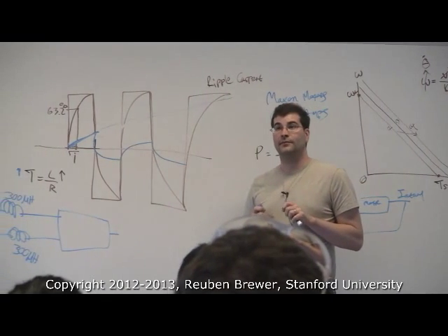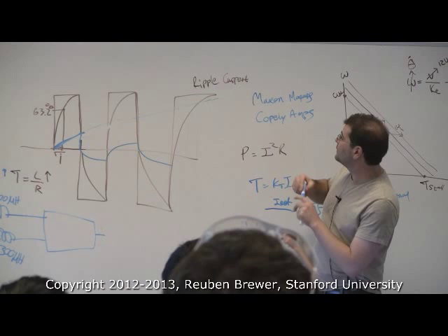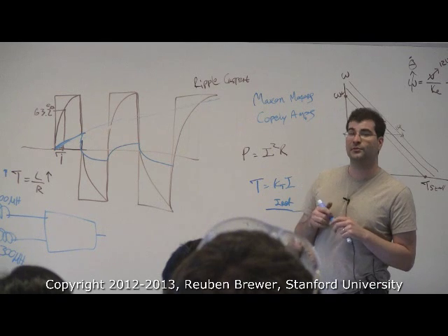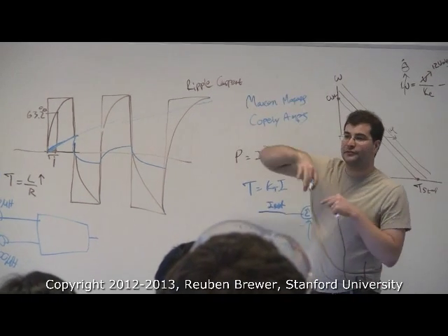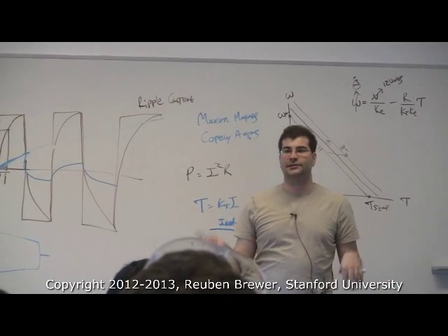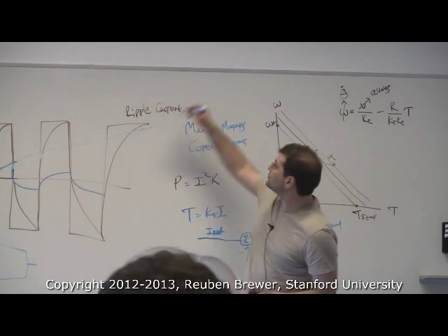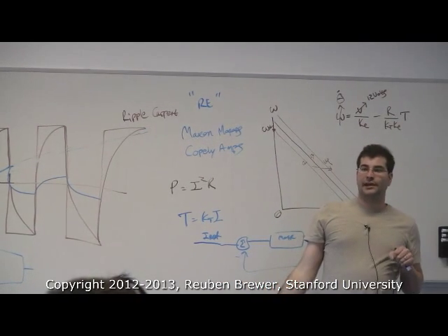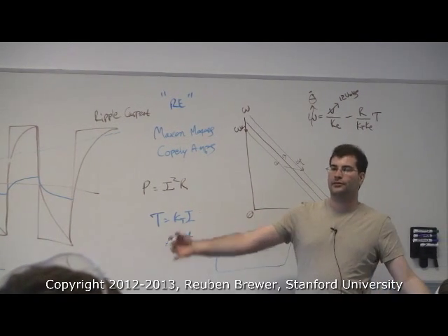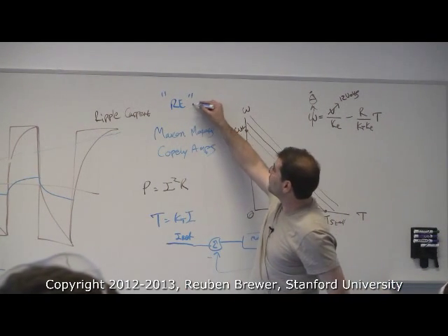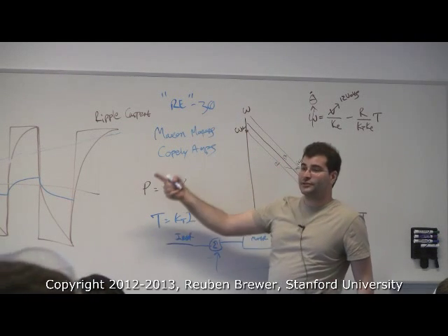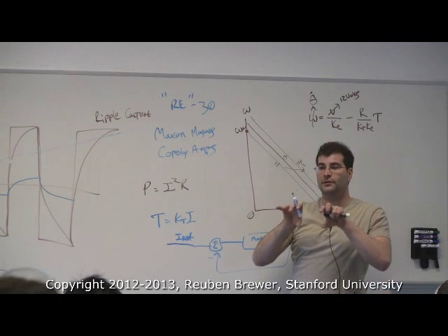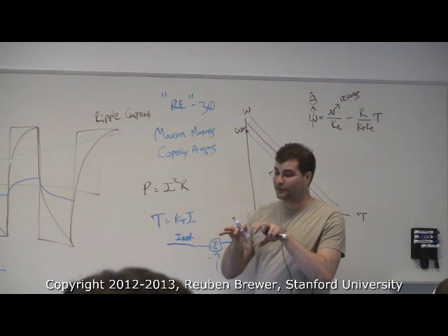Let's talk about Maxon motors. Who here knows the term RE in reference to Maxon motors? So only two people. Okay, so Maxon motors, they have different series. They have A series, A-max series, RE series. Most people who do research in haptics use the RE series. Then the next thing you do is you say, I like the 30 millimeter motor. It smells good. So I'm going to do an RE30. RE-30 means it's RE series, and it's a 30 millimeter diameter motor in terms of the overall core of the motor, or the outside.